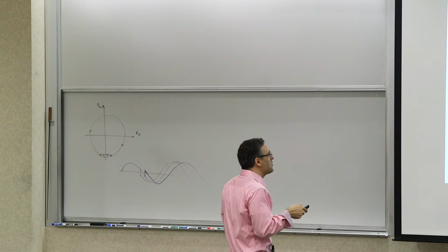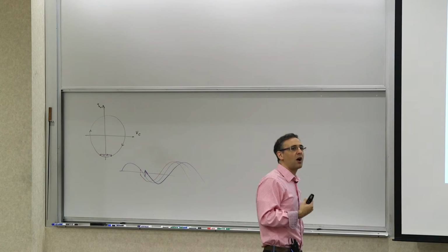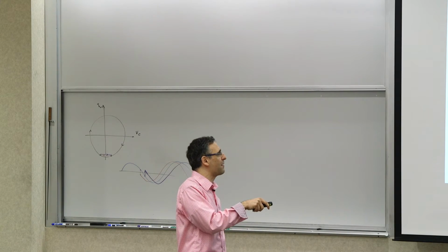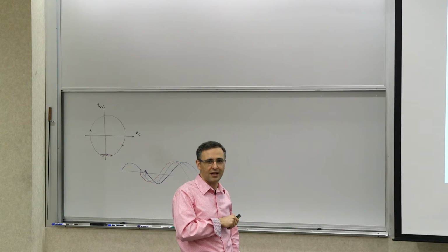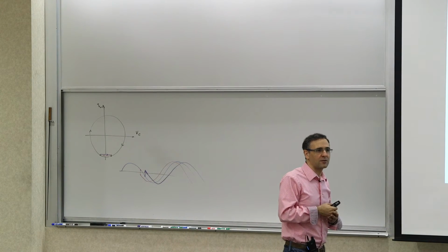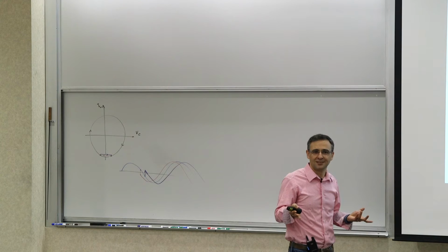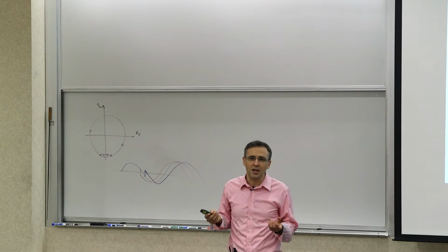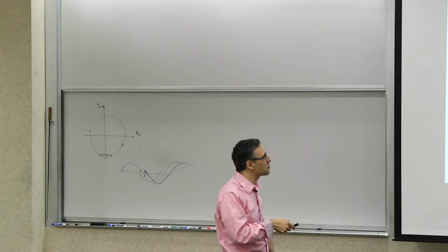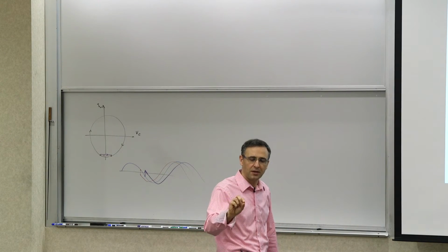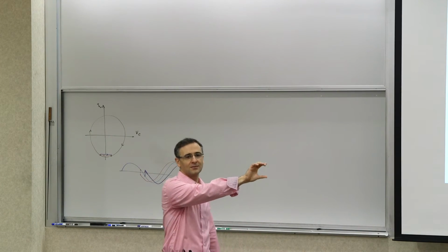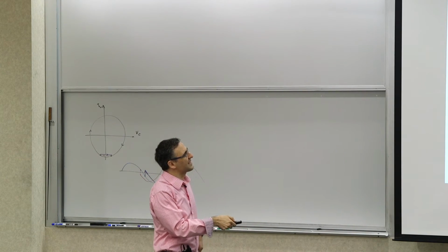Now, if you look at the channel noise due to this process, what does it look like? If the transistor is off, it's not going to be generating a lot of channel noise, because there's no channel to produce noise. So it only produces noise periodically, when the current flows. You can see that this noise is periodically going up, coming down again, going up, coming down again, and so on and so forth. So this would be a sample of that.